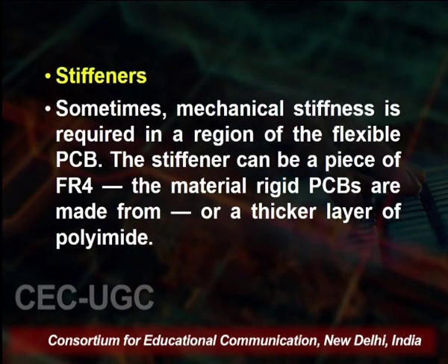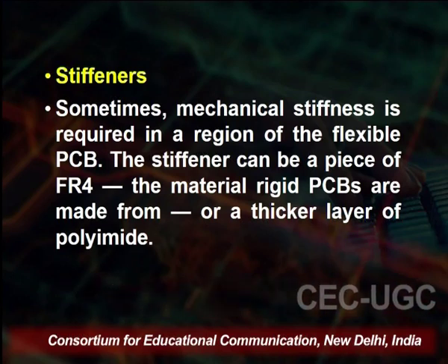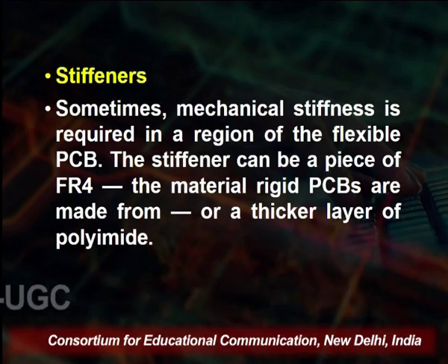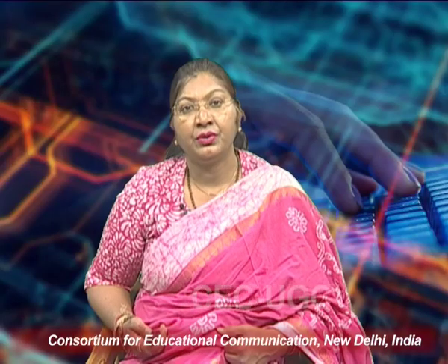Sometimes mechanical stiffness is required in a region of the flexible PCB. For this we use FR4 or a thicker layer of polyimide. So, these are the basic polymers used for flexible circuits. In this type of circuits we have defined many types of flexible circuit.